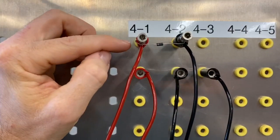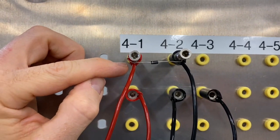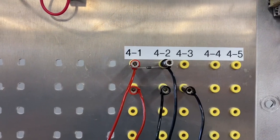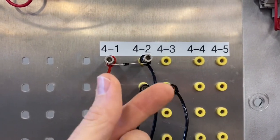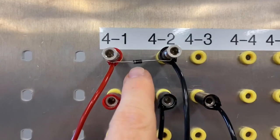And that's where I wanted to point out this kickback diode that we have here. This kickback diode is to mitigate the inductive kick created by the solenoid. The solenoid is basically an inductor, and when you turn power off to it, it wants to oppose the change in current, so it makes a reverse voltage. It gets really, really high. So I put a diode here. It's in backwards.